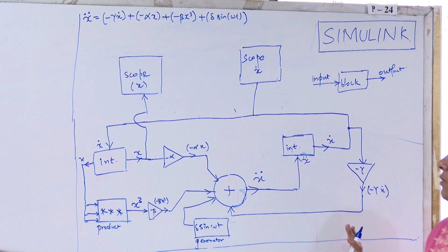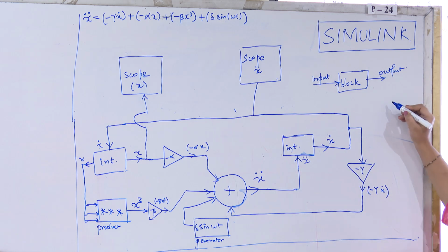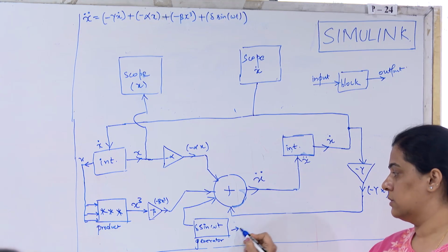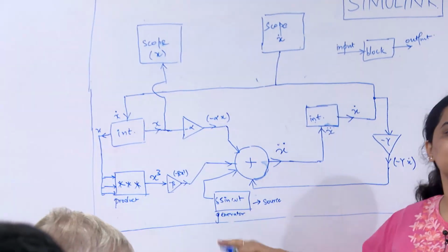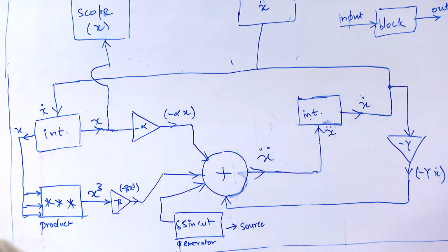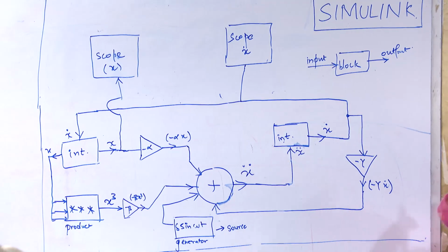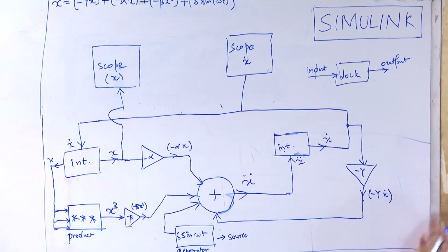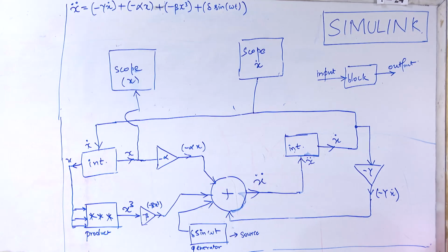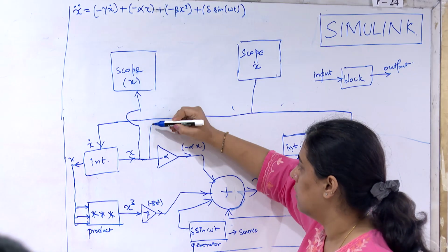Okay. So for Simulink, whatever you are giving to the block diagram is called a source. So this is also a source. You are giving it inside the block diagram, right? When you want to take something out of the block diagram, you will have to put a sink. So you want a sink for the workspace. You want all your variables to be stored in the workspace of MATLAB while the code is running. So you have to put a workspace sink. It basically syncs everything to the workspace. So one sink I can put here for x.